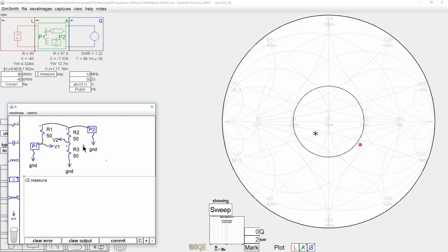And this circuit right here, no matter what this impedance is, if this impedance is incredibly high, this resistor doesn't matter anymore, and the generator sees 50 plus 50 or 100 ohms, or 2 to 1 SWR. If this is a dead short, it sees 100 in parallel with 50, which is 33. It actually sees worse SWR up here, so you could make these resistors even lower, make them say be 40. You could make it symmetrical. But in the way it's shown right now, the SWR will always be less than 2 to 1, which is not really bad for most transmitters.